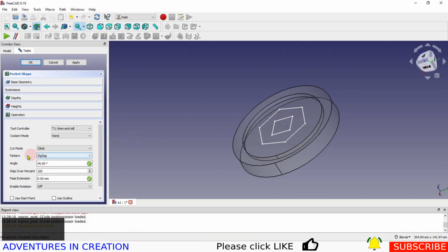And I'm going to choose a pattern. If I choose zigzag, if I let it choose that zigzag, it won't clean up around the edge. So what you need to do is zigzag offset, and then that will clean up around the edge when it does the zigzagging. I'm going to change my step over to 80.